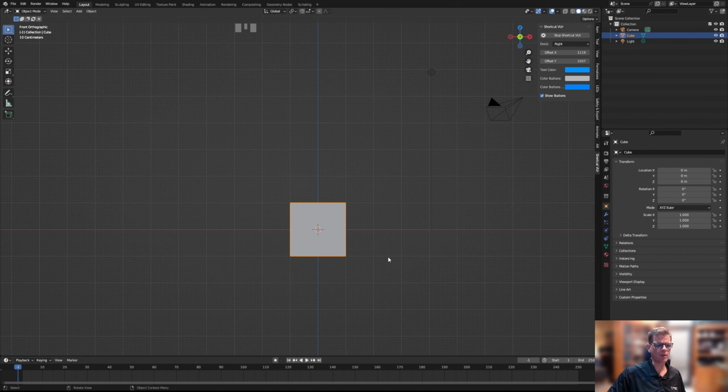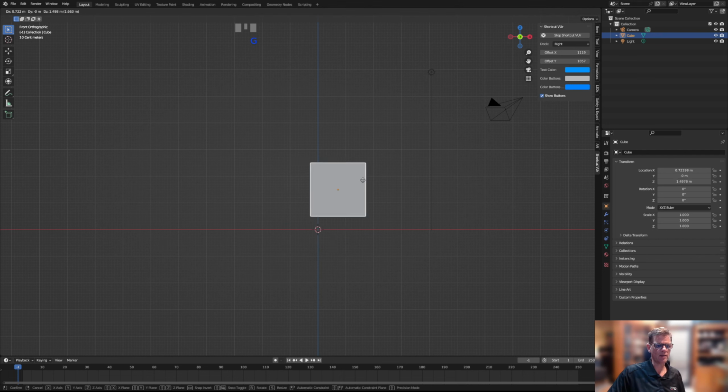It just turns out when you're moving objects around, which let's do that. Let's learn how to move an object around. I've got the object mode, I've got the cube selected. Just going to hit G, and by hitting G I can then move this object around. And one of the advantages of being in this view is that I know it's not going to move it at all in the y-axis. It's just moving it in the x and the z axes.